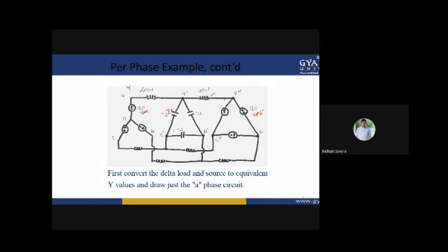That is the beauty of phasor solutions. That means when we are using the phasor components, we can use only the single phase values for the analysis. Okay. So what do we mean by single phase? That means we will be using only phase A and draw the equivalent circuit for it. Okay, and then we will evaluate it. That will be similar for all.